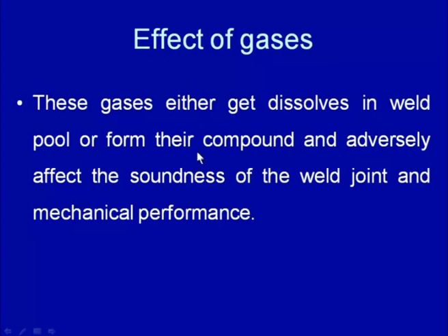And if these remain in the weld joint, they will adversely affect the soundness of the weld joint, which in turn will decrease the mechanical performance. So, these gases therefore must be expelled, or should not be allowed to be there in the arc environment, and for this purpose different approaches have been developed and are being used.